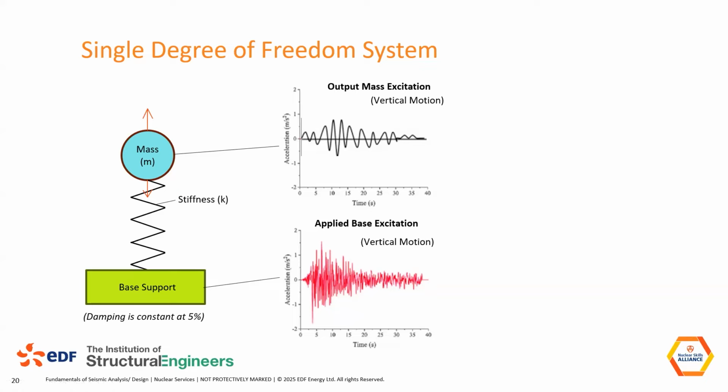So from this hopefully simple system, which I'm hoping you can follow, we're going to extract just two pieces of information, and they are two very simple pieces of information. The first is we're going to extract the frequency of this system. Sometimes you'll see F for frequency or omega for the fundamental period of vibration. It's simply root K over M, so root of stiffness over mass. This stiffness is a defined value, the mass is a defined value, 1 over the other, square root of it. That is the frequency of the system. And that's the first thing we're going to take from this.